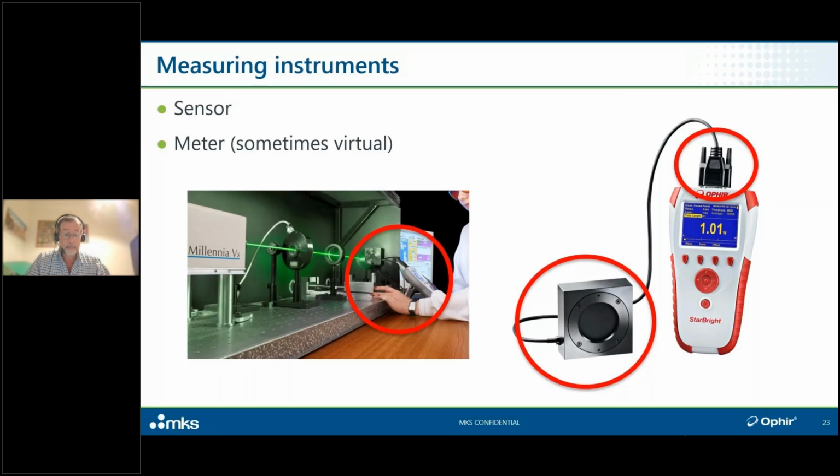The meter, some manufacturers call it a display, as I said, console, controller. Every manufacturer uses their own terminology. Now that's the user-facing end, which measures that analog signal coming out of the sensor. So Ophir meters are, in essence, very sophisticated current meters. It reads the calibration data in that EEPROM, processes the signal, which may include all sorts of calculations, and then outputs the measured reading, possibly via a numeric display for a human user, as in the example we see here, but there may be other ways, maybe through a digital interface to a PC with software running.